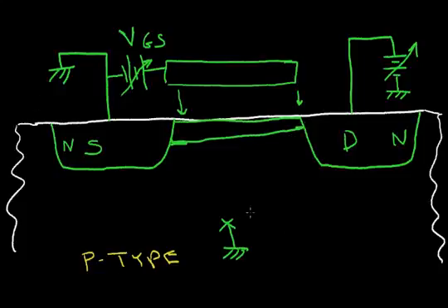So on my current versus voltage curve, my resistance is increasing. As the channel was driven down very far, it had lower resistance, but as this region is thinning down here, the resistance is increasing, and I'm diverging from this curve. I'm going to a little higher resistance, so this slope changes. Now, if I increase my drain voltage even more, let me erase some of this channel region.